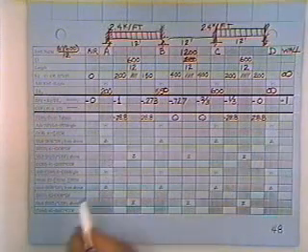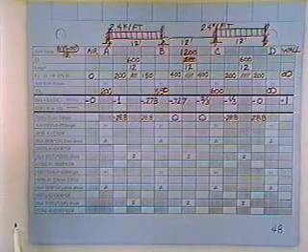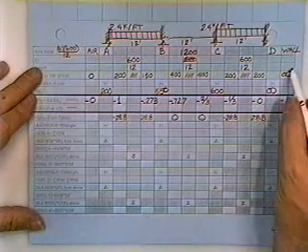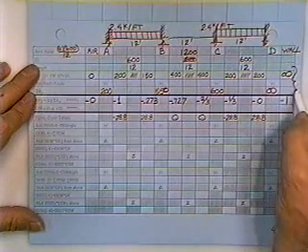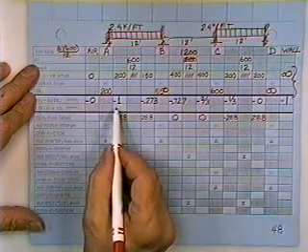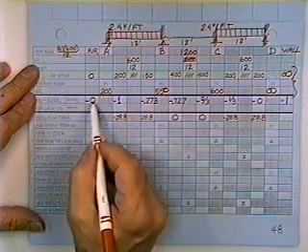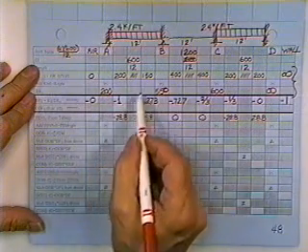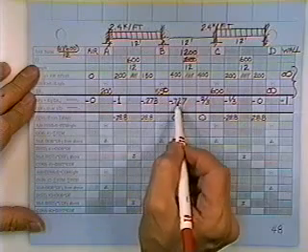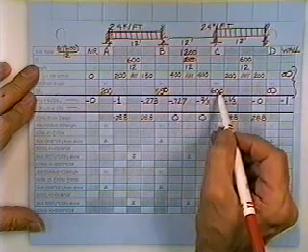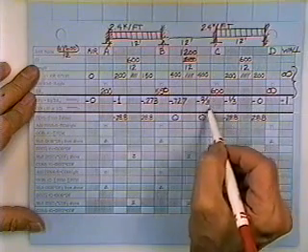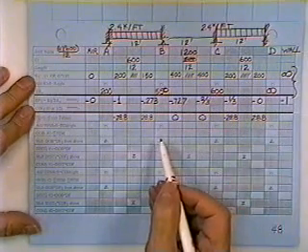The nice thing about this method is it's really confusing. It's really strange. It really takes some thought. Only in this region right here is it screwball. Once you calculate a couple of the numbers, man, you're on your way. 0 over 200, nothing. 200 over 200, 1. 150 over 550, that number. 400 over 550, that number. 400 over, and the little arrows tell you which ones go together. Those are your distribution factors.